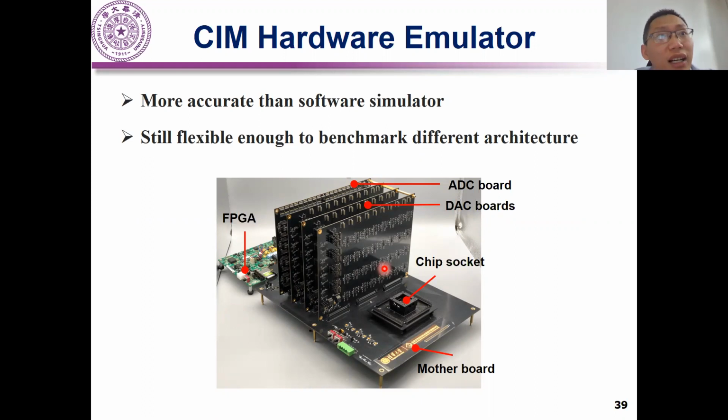And besides, this emulator is still very flexible. It's flexible enough because we can change the peripheral circuit very easily, and we can also change different RRAM array designs. We just need to change some PCB boards here. So it is very flexible. We can change the architecture and some circuits to do various benchmarks.